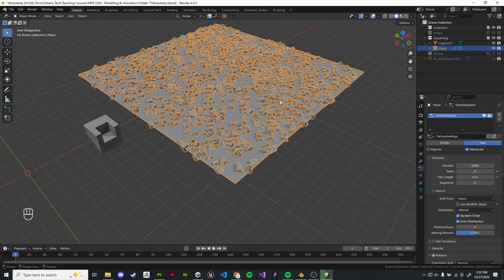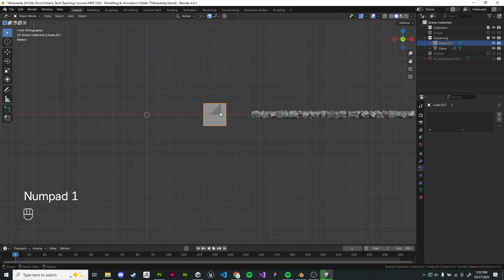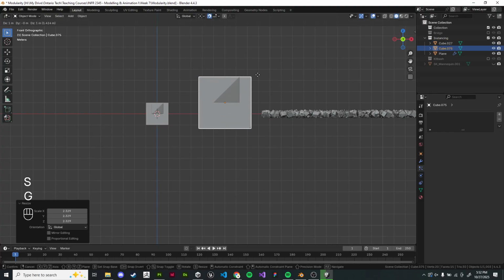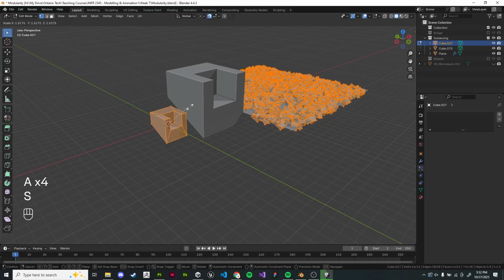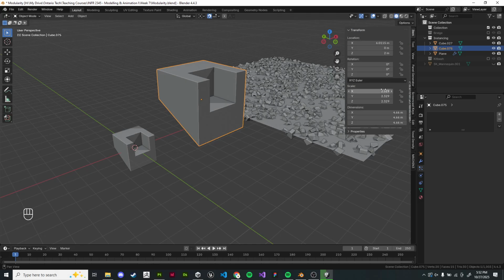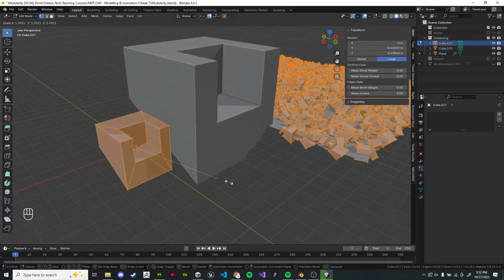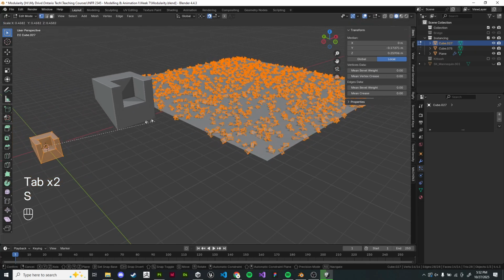Are you able to make a regular size version of an object and a bigger version of the object, but then when you scale the regular one, they both scale at the same rate? Sort of, kinda. So if I Alt-D this and make it big, and then I scale within here, it's still scaling, because this is using the object scale, which is set to 2.3. It's going to maintain that 2.3 size being bigger than this one no matter what. So it will always stay 2.3 times bigger. And if I edit the mesh and make it bigger, that will still get bigger too. And same with all of these, they're getting bigger as well.